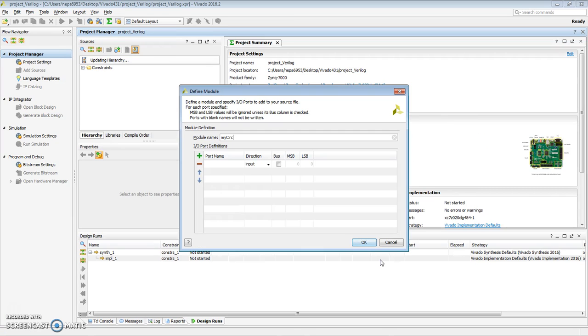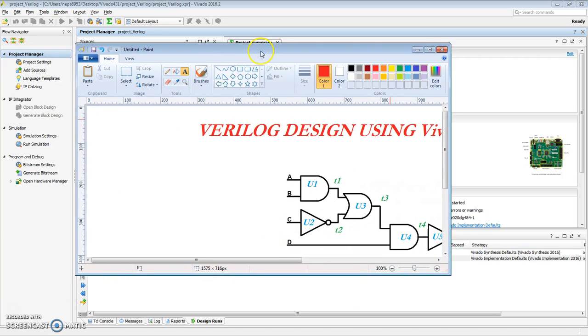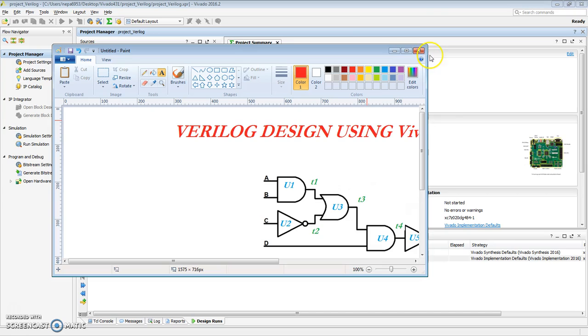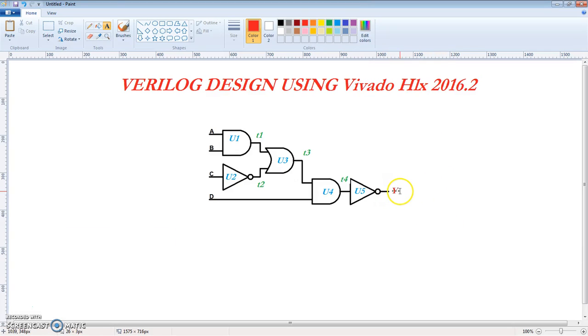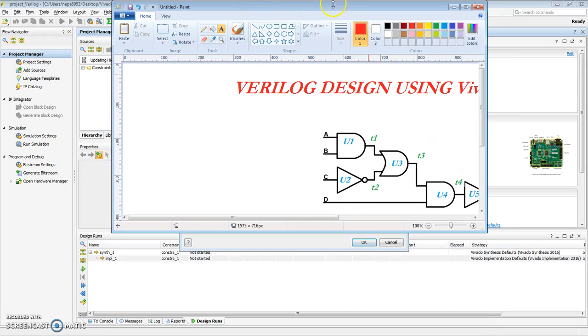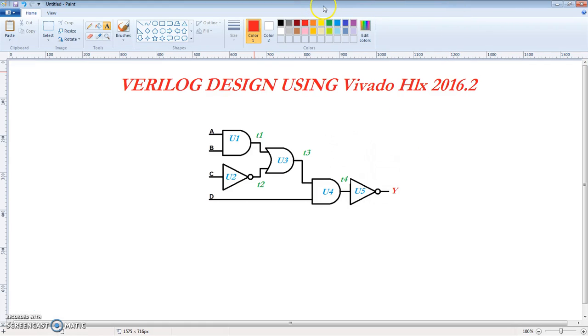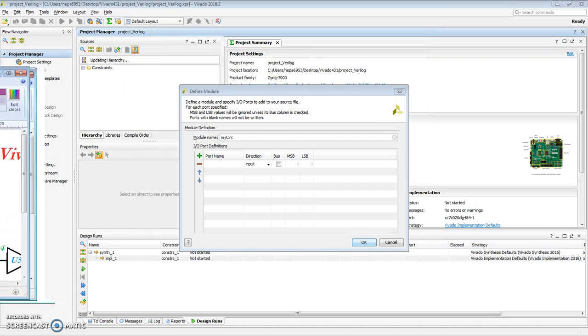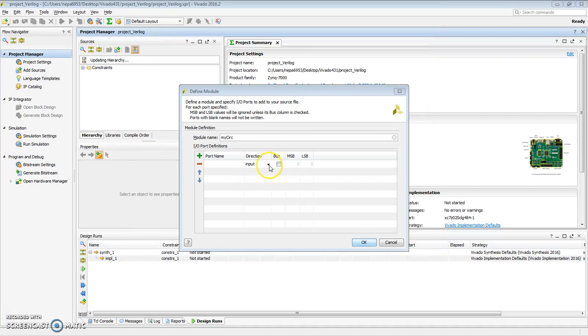Okay. Now for my module name, so that will be the name of the circuit that I create, and I call it my circ. That's the name of the module. You feel free to modify this if you choose. First thing we want to do is describe the inputs and outputs. So here's the circuit that we want to build. This circuit has an output called Y and inputs called A, B, C, D. The internal Verilog convention for built-in components is typically output is listed before the input. So that's what we'll do for our design as well.